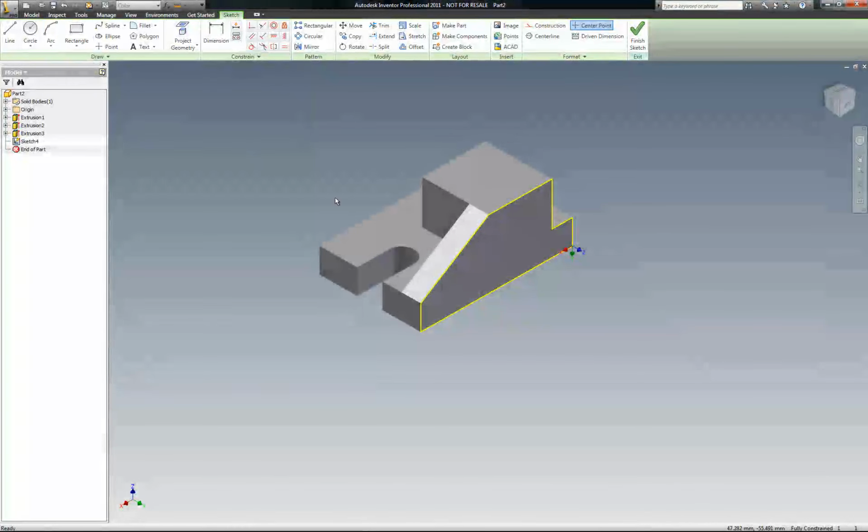And then while we're here, right click, new sketch. I can't make this circle and this little wall at the same time because one's an extrusion and one is a cut. So you have to do these two different operations. That's in the midpoint, I'm pretty sure. I have a radius of 12, so it's a diameter 24.